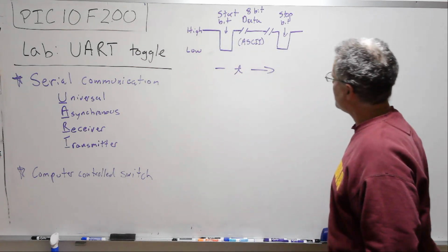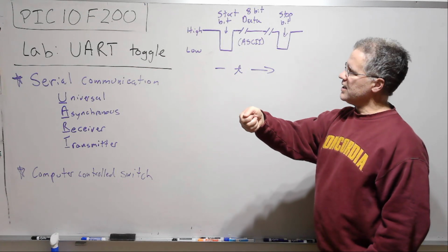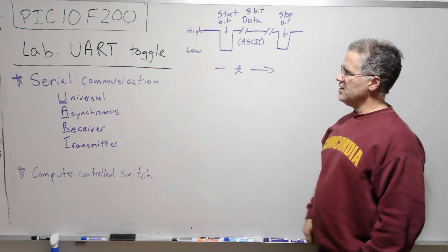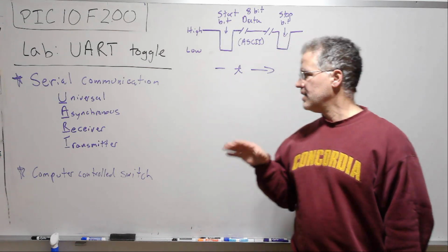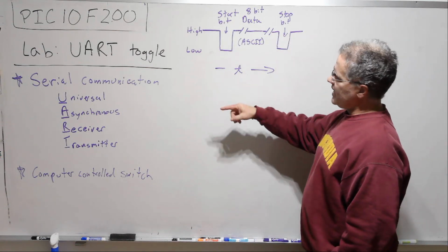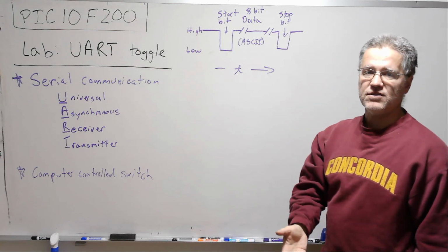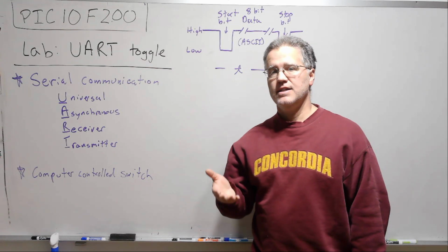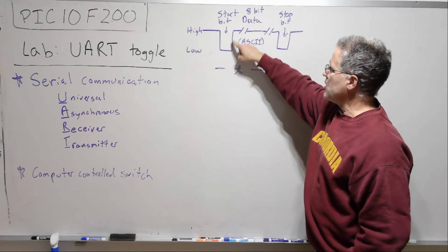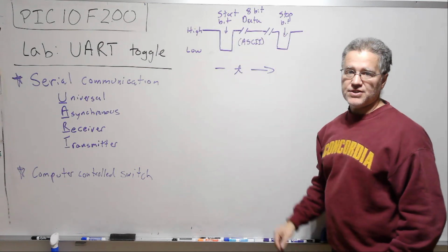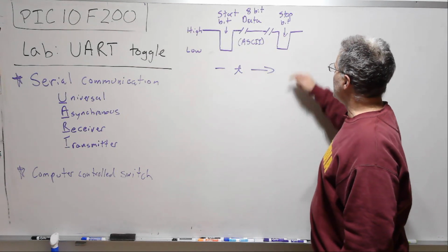All right, so essentially with the UART communication, you have a USB plug into your computer, and then you have some sort of UART device, and I'll talk about 3 of them here. In all cases, the data signal is held high, and then it's active low, so it drops down low to send data. The basic structure is it's high, then comes a start bit, then 8 bits of data. This could represent an ASCII character, for example, and then a stop bit.